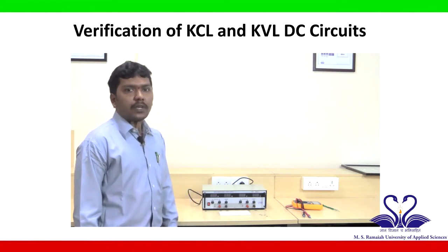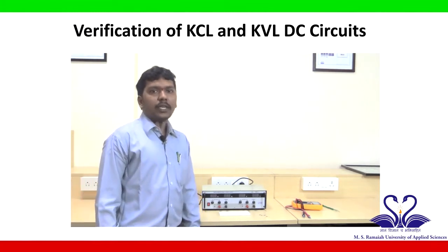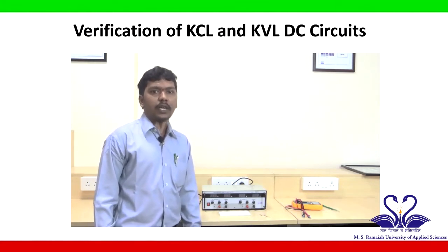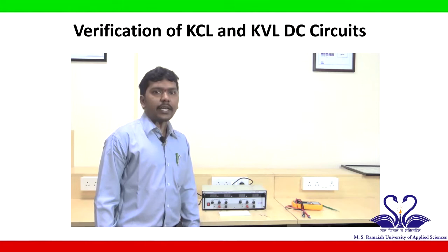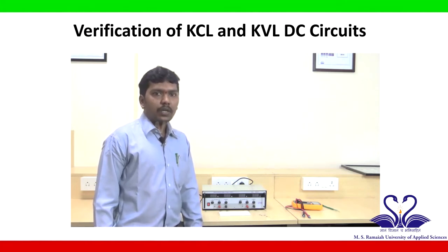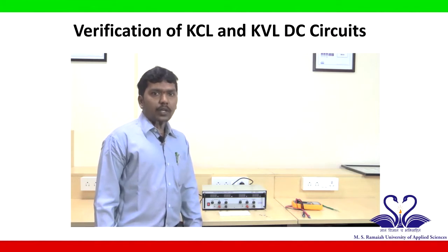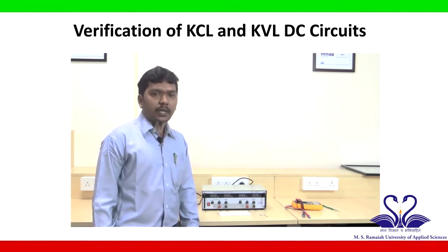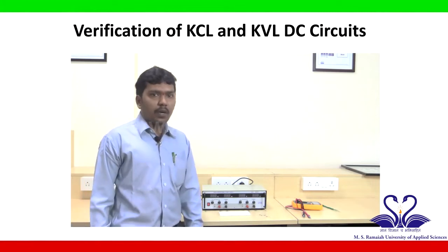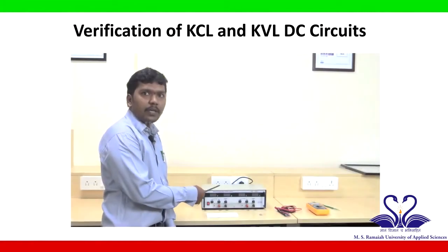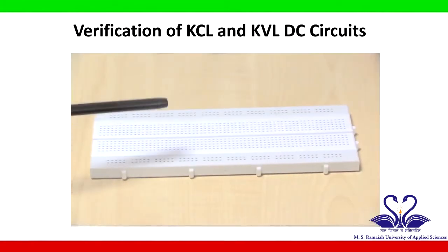The statement of Kirchhoff current law is, in any electrical circuit the sum of incoming currents is equal to the sum of outgoing currents, or it can also be stated as the algebraic sum of all the currents entering at a node is equal to 0. And the statement of KVL is the sum of applied EMFs is equal to the sum of voltage drops across the individual elements, or it can also be stated as the algebraic sum of all the voltages is equal to 0.